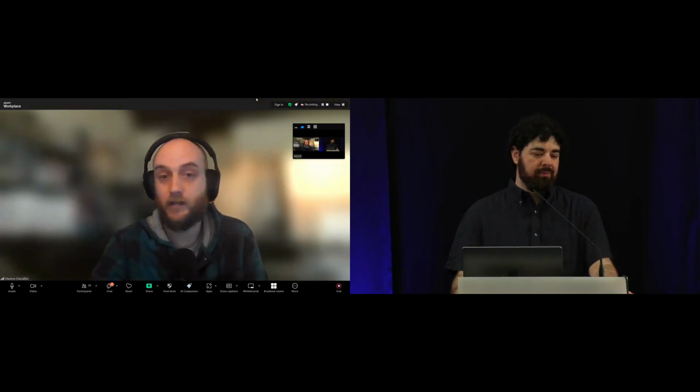With the PHY tool, it wouldn't really work because PHY tool is for Ethernet PHYs, which is a different beast than generic PHYs. The name of the generic PHY subsystem is really misleading, because here we are talking about PHYs for SerDes lanes. So they can be used by NICs, but also by USB, SATA, PCI, and all of these kinds of devices that need SerDes lanes, basically.